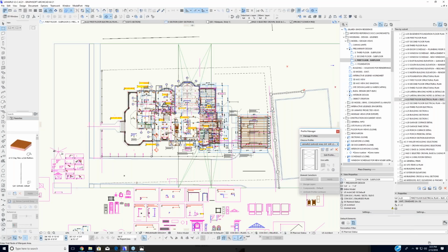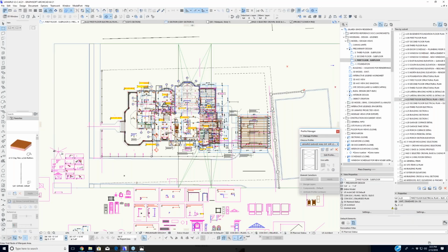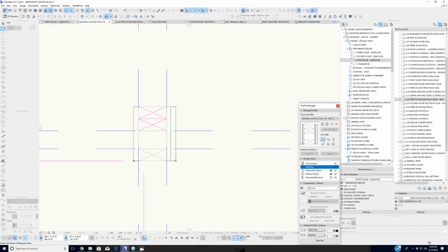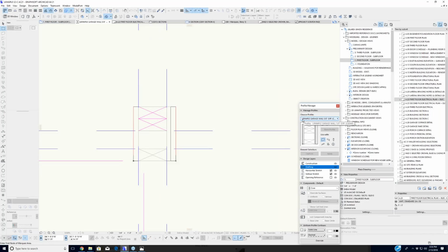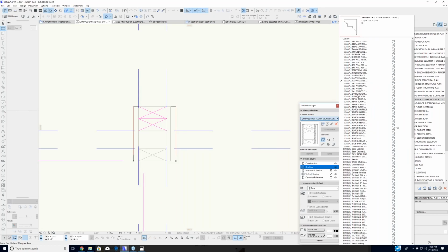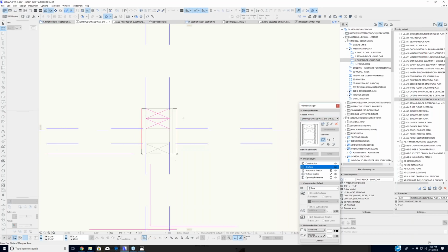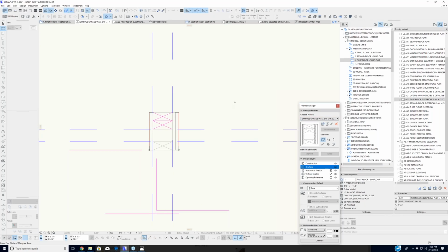Let's jump on this wall. I am not opening up that wall. I'm going to click edit. A wall like that, I didn't start from scratch. I'll start with a wall that's very similar, save it as something else, hopefully with this new name, adding 2 spaces so that it jumps up to the top alphabetically, and then go in here and alter this, make this bigger, stretch this, add another layer, and then save it. You're leveraging and reusing and adapting your existing body of work, which of course is the smart thing to do.